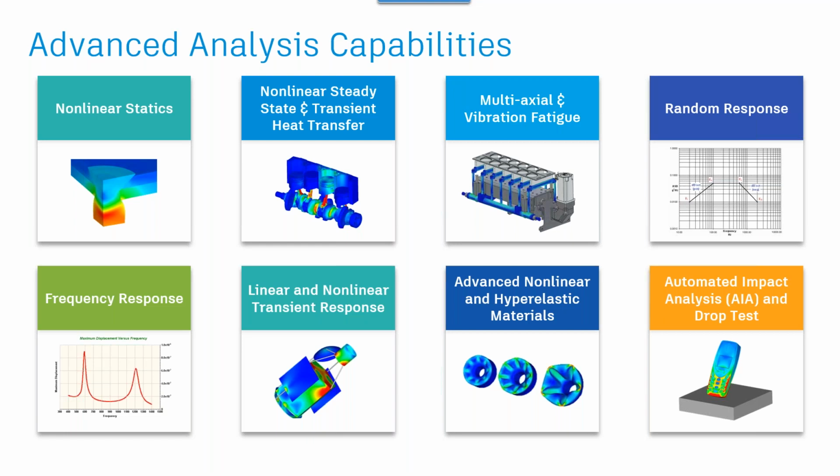Now, these are the more advanced analyses where not only are you looking at some kind of an advanced loading or boundary condition situation, but also the behavior of the part goes into a much more advanced state where your material could be required to simulate the nonlinear part of its material curve, as well as the hyperelastic side of the material behavior. So again, with Inventor Nastran, you can set up these simulations in your CAD environment, have those different boundary conditions and different material behavior defined for this part that you're trying to simulate.